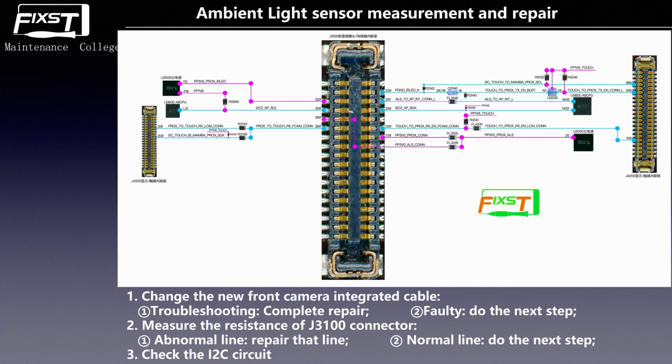First, we need to talk about the main function of this IC. It provides the power for the display, touch, and pressure sensor circuit. And for this IC, the U4000 display touch power IC, to work normally, it also has two conditions: one is power, the second is signal. As you can see in the slide, you can see the line. Its power is from PP VCC MAIN. And its signal, one part is from the PMU, one part is connected to the CPU.